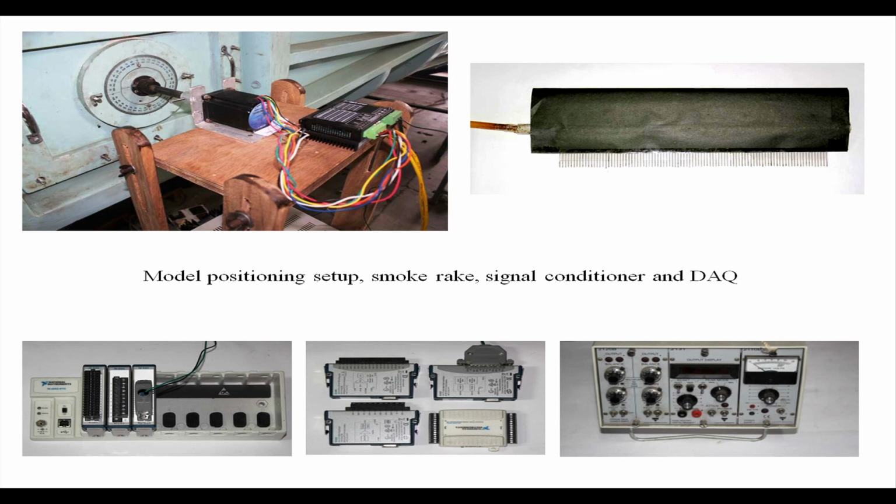So, it depends on the section, and the point is that if you are fixing it at a certain angle of attack, the pressure difference remains more or less time invariant, until and unless you have pitched it up to a fairly large angle of attack, where the airfoil sees a lot of flow separation, so to say.